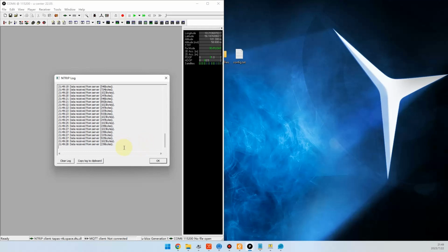The good thing is that you don't need to establish your own base station in this way, but sometimes it's not that accurate if the rover is near a building or something like that, because there might be interference. Yes, that's 3 ways of establishing RTK with the C099-F9P boards.